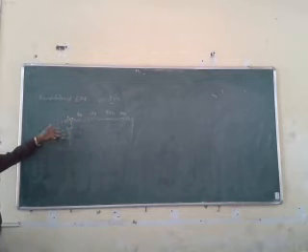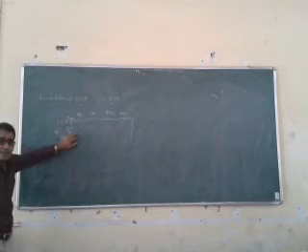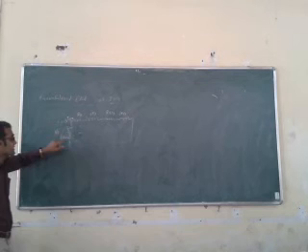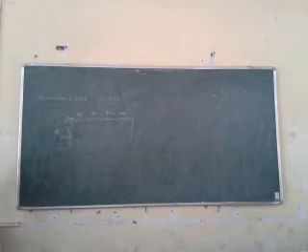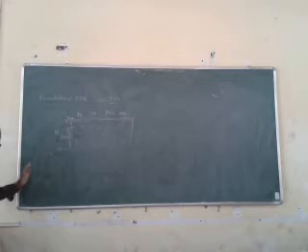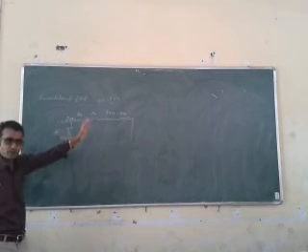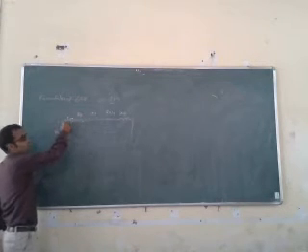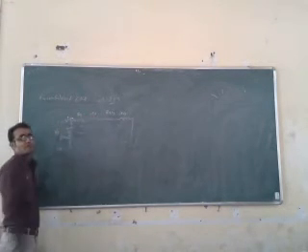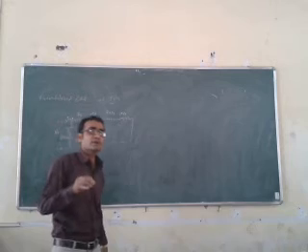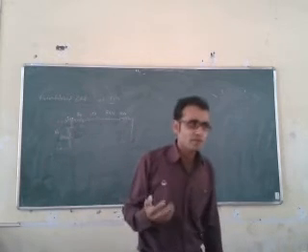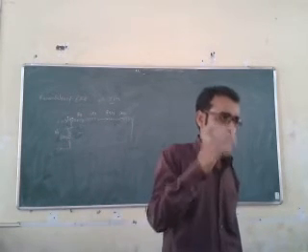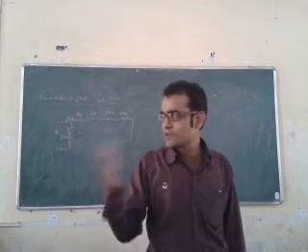But for the sake of further understanding, yet we remove the value of the resistance, yet we have connected the value of XM. Is it clear so far? The circuit has changed from where it started: first it was straight, then we moved it to the middle. This is the input current, and the current passing through the stator is the same current passing through the rotor. So we are saying that the rotor current is now referred to the stator.